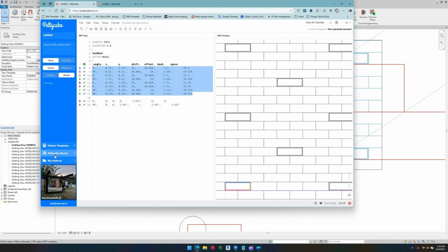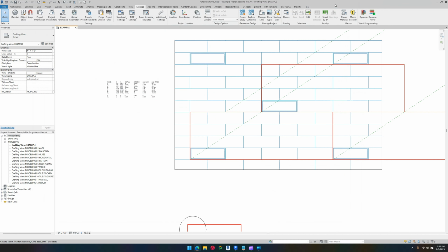They have some libraries for preset families of patterns that people have already made. And you can export to CAD, millimeters, drafting, whatever. But I use it specifically to help me visually create the pattern when I don't really want to do it by hand with pyRevit, or when I want to make sure the family is a little bit more efficient.